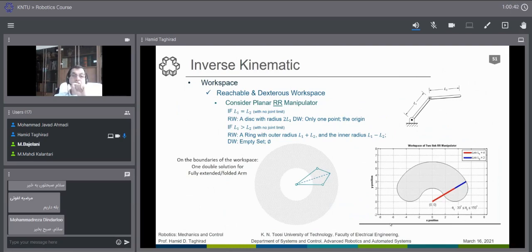And that means that we should solve the inverse kinematic problem, not just at one point, but at consecutive points. Which point is very interesting. Suppose that we have this point, we have, let's say, 8 solutions for that. We find one of the solutions which is appropriate to that. Then we go to the next point, which is a bit different from this. We have, again, 8 other solutions. Which solution do we choose? We choose the solution which is very close to the previous one.